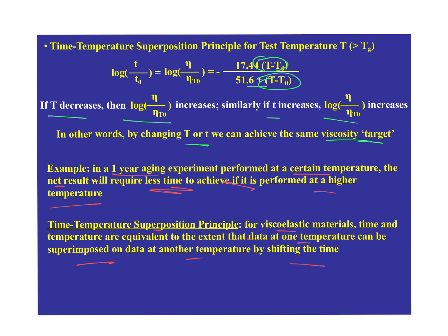So you can get to the same endpoint with two different approaches, either increasing the temperature or letting it sit there for longer periods of time. And unlike a lot of other things, those are kind of equivalent in polymers. It actually works pretty well. You can go back and forth, unlike a lot of other simulated aging processes that don't work well if we try to increase the temperature.